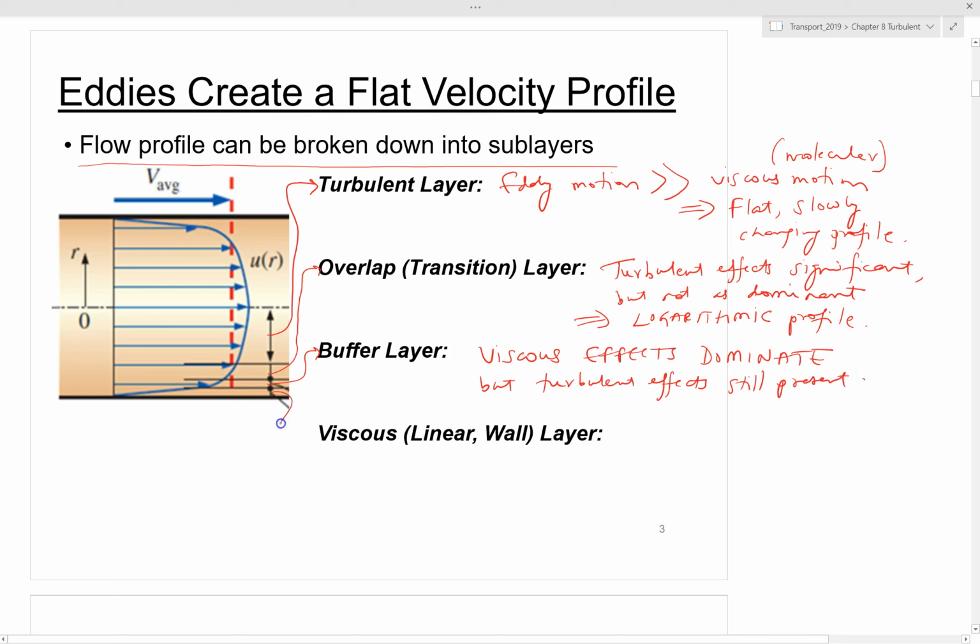And finally you have the viscous layer, which is very thin, quantitatively about 0.01 of the diameter, and it's a linear profile.